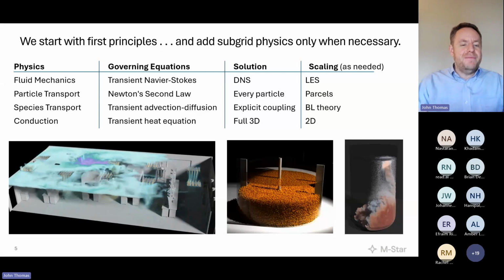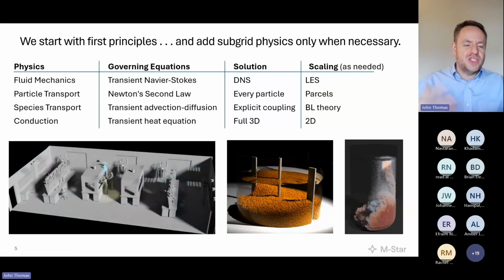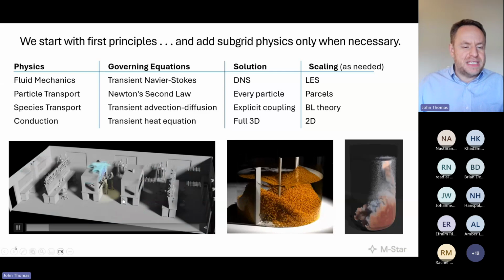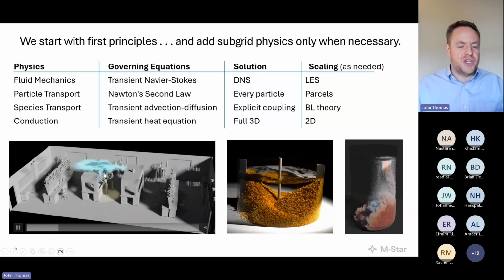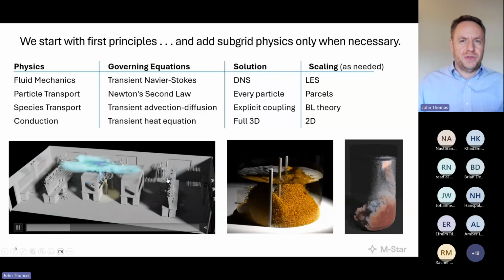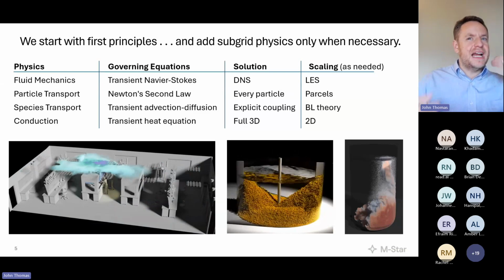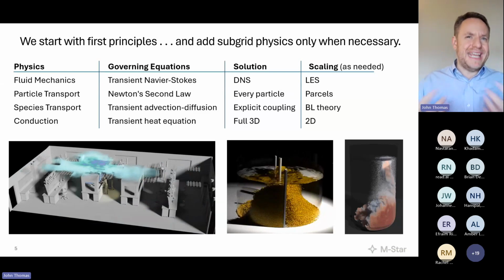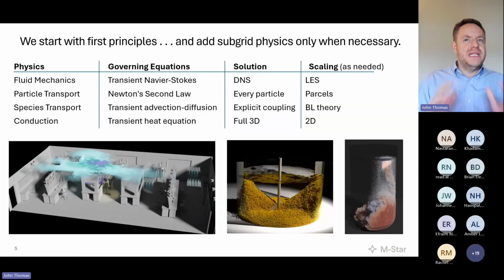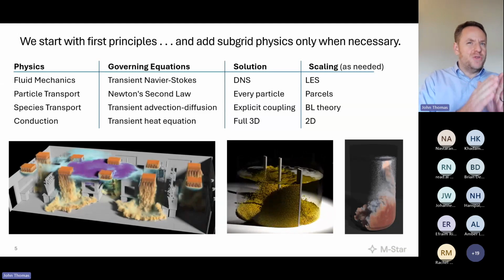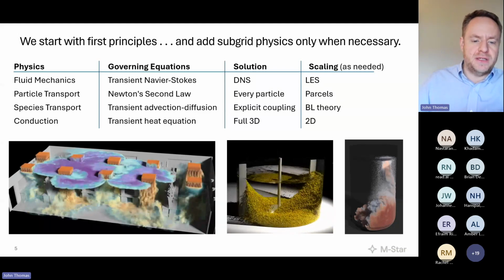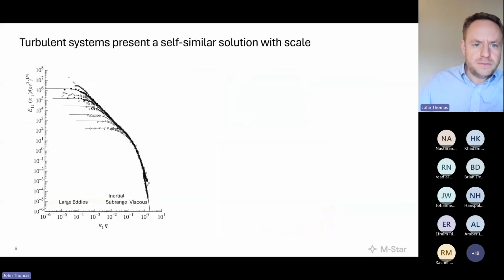This idea of time-accurate, three-dimensional, inline controlled, multi-phase, multi-species simulation, tracking concentrations, tracking particles, that's in play. And it's not just in play, but it's routine, as it were. And in fact, for many of the simulations, we can beat real time, which is neat to understand for a facility design. Okay, I want to touch on this point about scale.